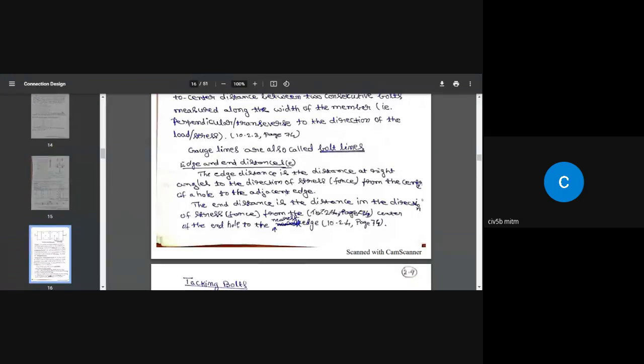If the bolt diameter is 16 to 22 millimeter, for example a 16, 20 or 22 millimeter bolt, you need to drill an additional 2 millimeter extra. That is, for a 20 millimeter or 22 millimeter bolt, you need to drill a 22 or 24 millimeter hole, as given in the code.